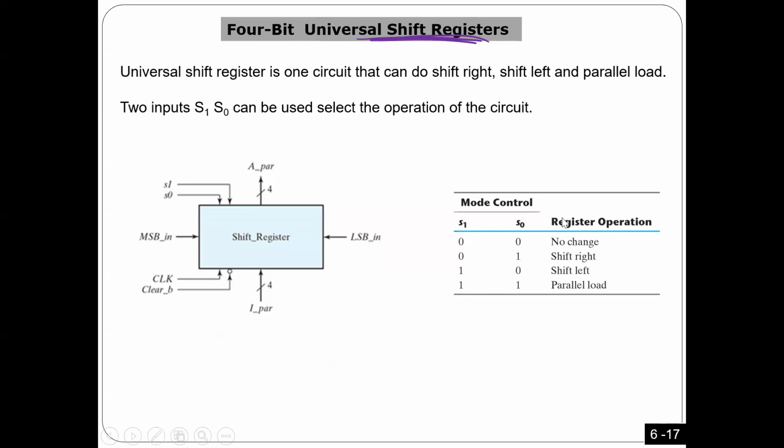What it means, look here guys, very easy. It means, for example, you have a parallel input. When I put it this way, put 4, that means something. So you have here 4 inputs for parallel load, and you have 4 outputs this way. Also, this one is universal. You will understand why it's universal, because you can do shift left, you can do shift right, you can do parallel load. You can do 3 things, based on the selection here. You have 2 selection inputs here.